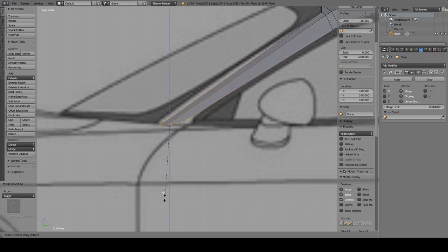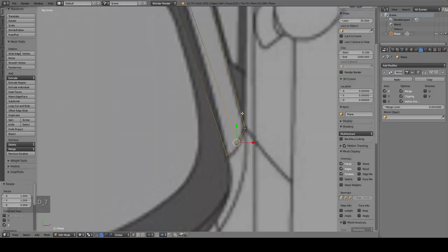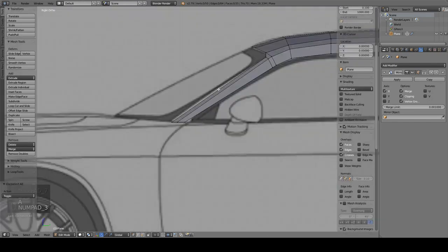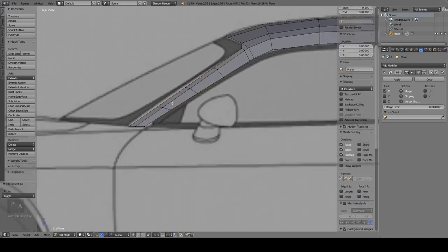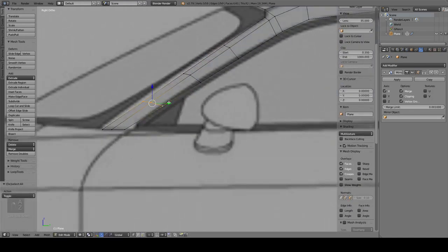And while you're selecting this, you can type in a specific value amount. And if we're scaling along the Z axis and you click 0, that'll basically just center them, align them, straighten them out along that axis, or Z axis. So now that that's straight, I'm just going to add a couple of loop cuts, maybe 3. Remember, we can just scroll on our mouse wheel to increase that amount, and then just double left click to confirm that.